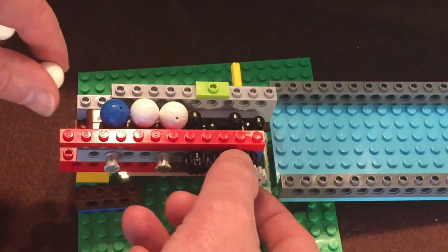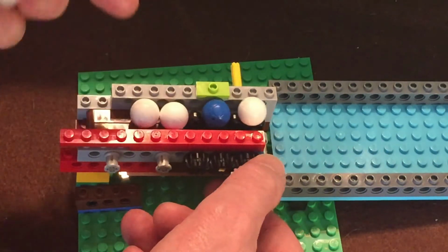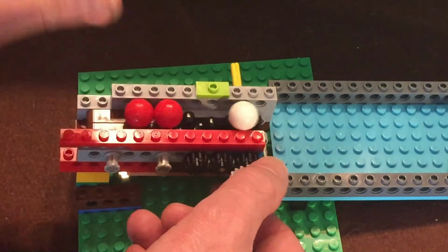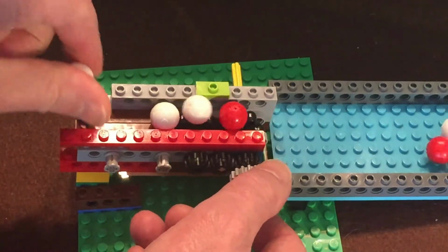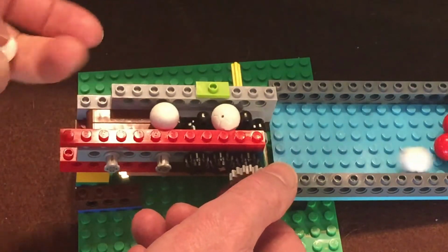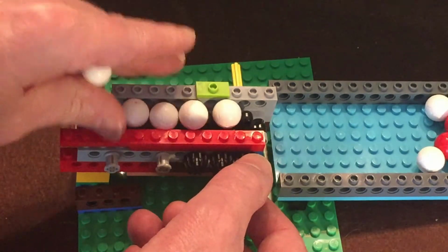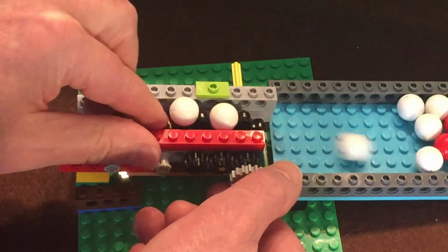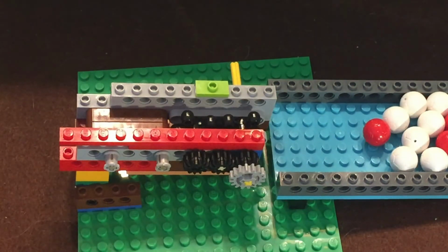Here I've got a really simple spacer built using four knob gears, also known as knob wheels. This one has to really be geared down because it will naturally pass four balls per cycle. That is, it will spit out four balls for each revolution of the knob wheel. Jamming isn't an issue with this design, but push is. Because there's not a lot of material holding the balls back, if they arrive with any kind of speed or force, they are able to skip right across the top of the knobs.